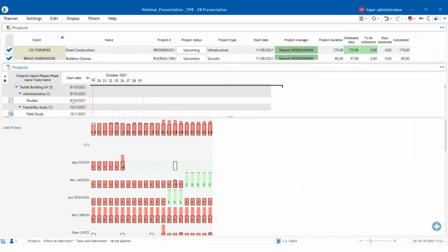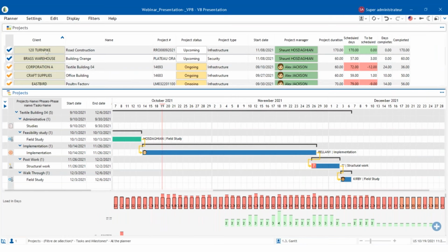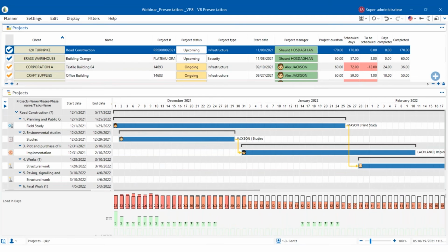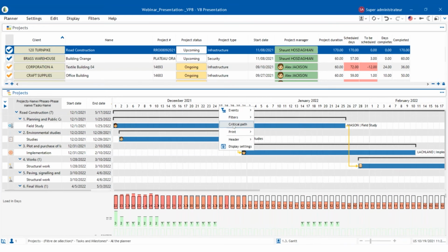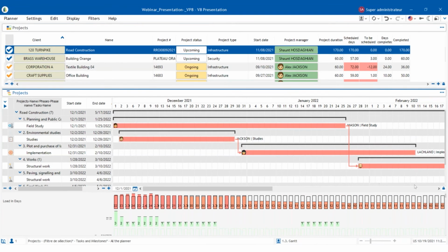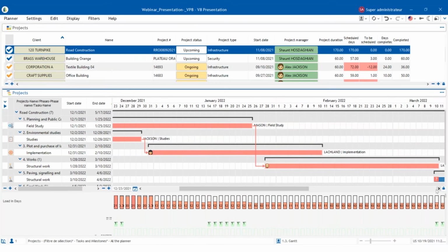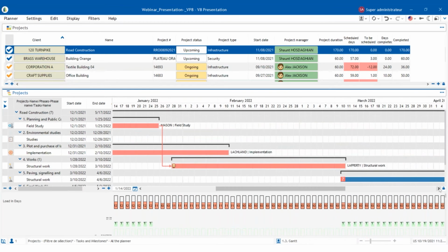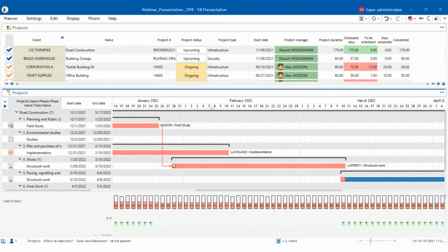Now, the other functionality we have here is a Gantt chart. So any project that has many activities on it, we can provide a Gantt view, which is what you see here. Now, more and more we're finding that a lot of construction efforts include or are considering critical path. So what we've enabled here is that if I have this, I can just click on my calendar, I look at my Gantt chart, I click on critical path. This is going to give me required steps to completion. Okay, so it's as easy as just clicking on a button from your Gantt to your critical path.